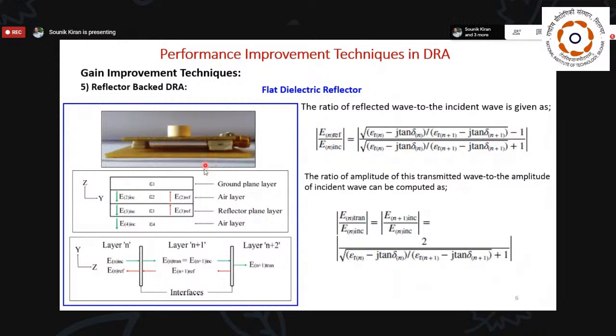And again, on the bottom side, below this reflector, we can have an air layer, which is normally nothing but the atmosphere. So what we see here is that the antenna is here, directly the resonator antenna, and the microstrip line is given here, and it starts coupling the energy through the slot at this point. At this moment, some amount of energy also comes towards the back direction. Back direction is nothing but the below direction, I mean it just moves into this air layer area. Okay, and when that moves into the air layer area, it will definitely be incident on a reflector.